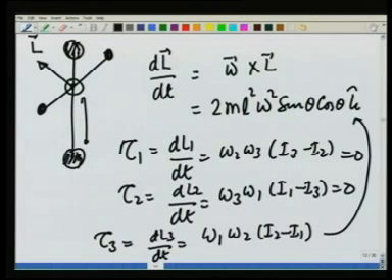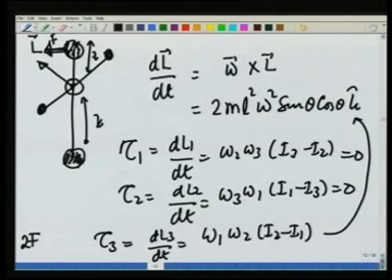If this height is z and it is symmetrically placed like this, then when the body is in the plane of the screen, the force here would be like this, and the force applied by the bearing on the axis would be like this, so that there is a torque coming out of the paper. The magnitude of the torque will be equal to 2Fz, where F is this force, and therefore I can also calculate how much force is applied on the axis by these ball bearings.